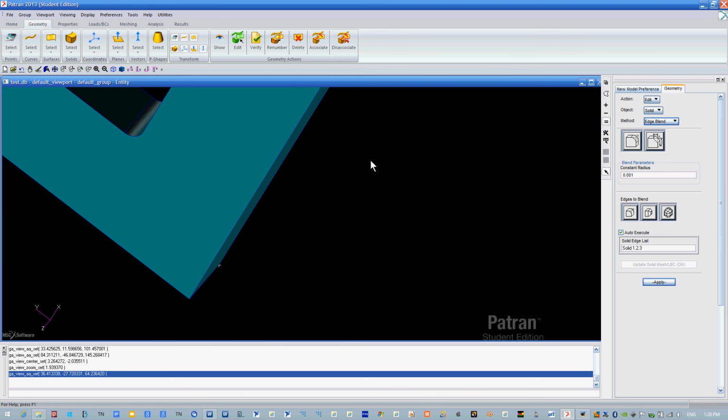I don't know if you saw it, but there was a fillet there. It was just extremely tiny. Even when it comes to doing the analysis, you'd still need that if you have an internal angle. In this case, where I applied it, it's useless, but it's still necessary for the analysis portion of it.